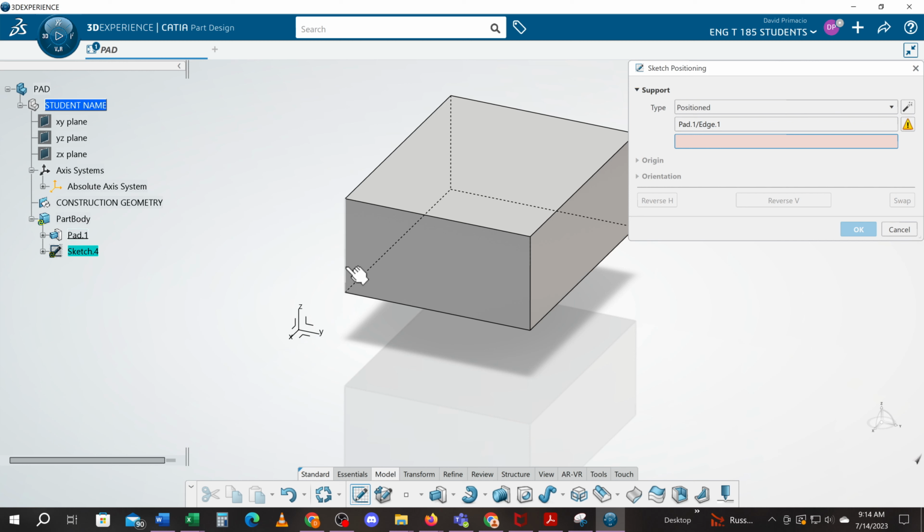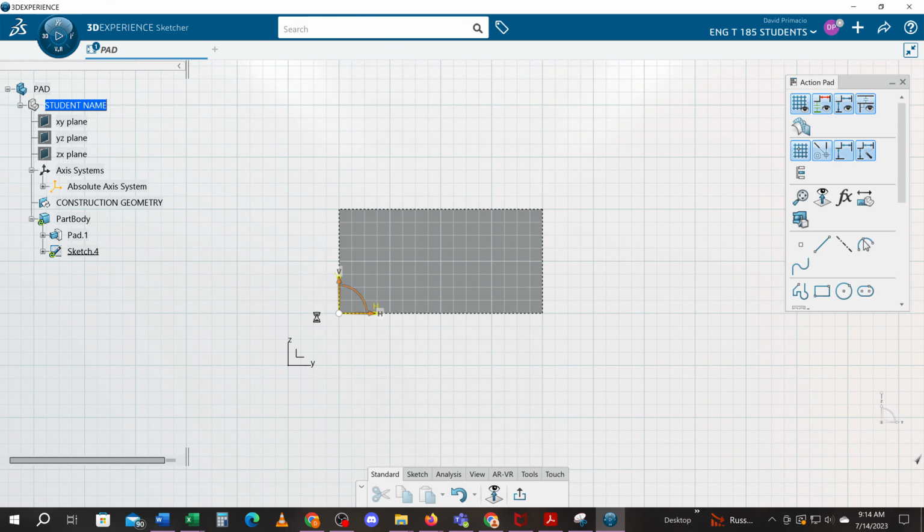line. So again, how I selected the datums, I select those in the same order. This is my horizontal, this is my vertical line. You'll notice it has this active. If these don't come up, you have to click this icon here to allow you to pick those lines. If I hit reverse vertical, I can select OK, and now I'm working on this corner here.